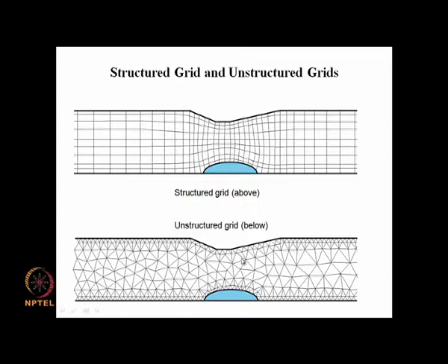In the case of the Poisson equation on this triangle here, we will have one neighbor here, one neighbor here and one neighbor here. So, the equation for this cell will have the value of phi at this centroid, this centroid, this centroid and this centroid. So, it will have 4 variables involved in this, and in this particular case we will have 5 variables, the point ij itself and the 4 neighboring points.